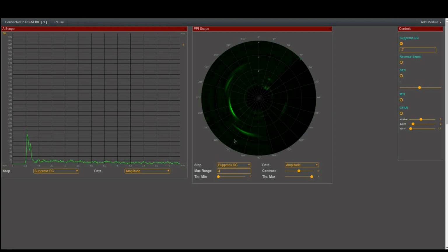So the background noise is getting stronger. There's me standing and Iman, so lots of noise. Now the computer screen where we measure. So let's clean up the mess, friends. How do we do that? We do that with the threshold. Later we start doing things like this with CFAR. But now let's learn the basic functions. So you see we simply suppress the small noisy signals, the walls there.